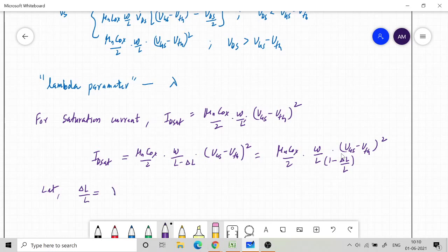This is going to be proportional to VDS, so larger is the VDS, the larger the change. This is a model that we fit to this change in length. It is a modeling in order to take into account what is called channel length modulation. The channel length reduces as you increase VDS by a large amount, and the fractional change, I am approximating by lambda into VDS.